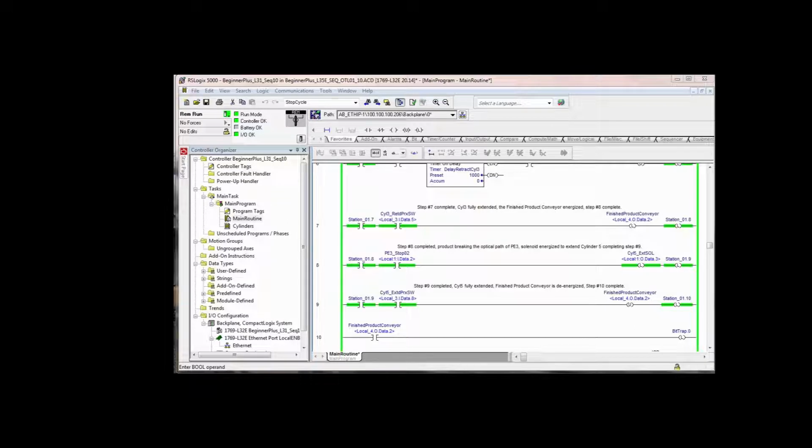Remember that this software is animating this graphic image that you're looking at. RSLogix does not exist except offline. You've got to keep reminding yourself. I mean, it's okay to think of it as being what's in the controller, but the controller has something that is logically identical, but not graphically identical. You don't have ladder logic diagrams in the controller. So in order to allow you to monitor what's going on in the controller, you have an offline program that you're looking at. Right now we are looking at the offline program because there is only one ladder logic diagram program for you to look at, and that is the offline version.